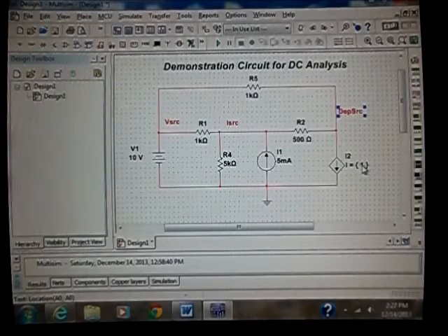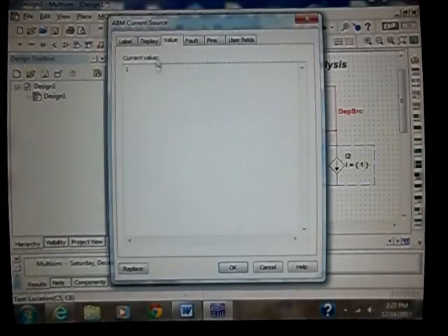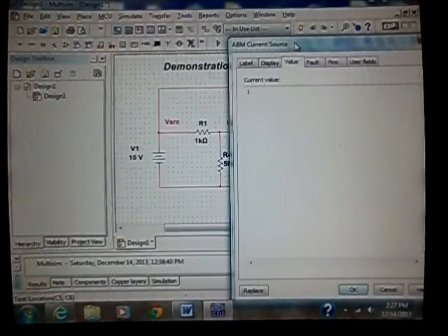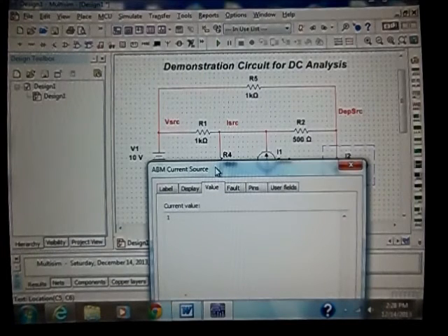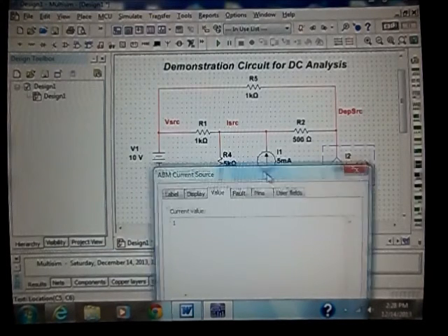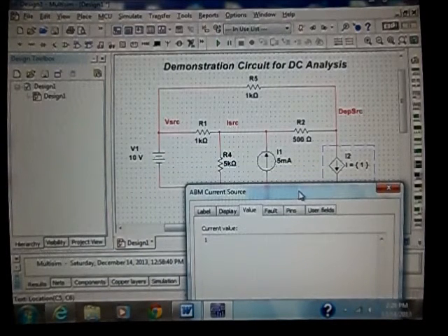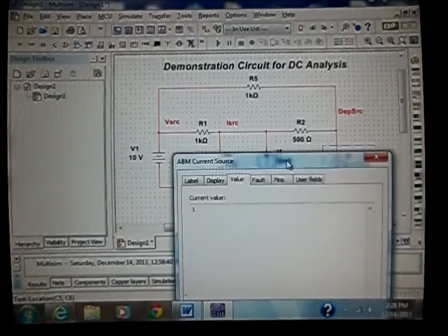Now, let's click on the strength of that dependent current source, and I can enter a formula to indicate what it depends on. And the way you indicate the voltage from here to here, plus on the left, minus on the right, is using capital V parentheses. So I'm going to multiply the strength of this source by 0.0005 Siemens.